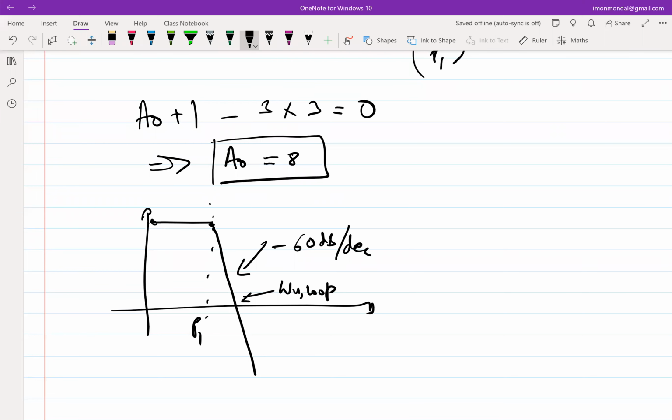So if you could change only one thing, what would we change? If you had 3 poles here, right? You take one of the poles and move it to lower frequency. So you move this pole, maybe I should have more space. You take one of these poles, move it to lower frequencies so that it goes by 20 dB per decade.